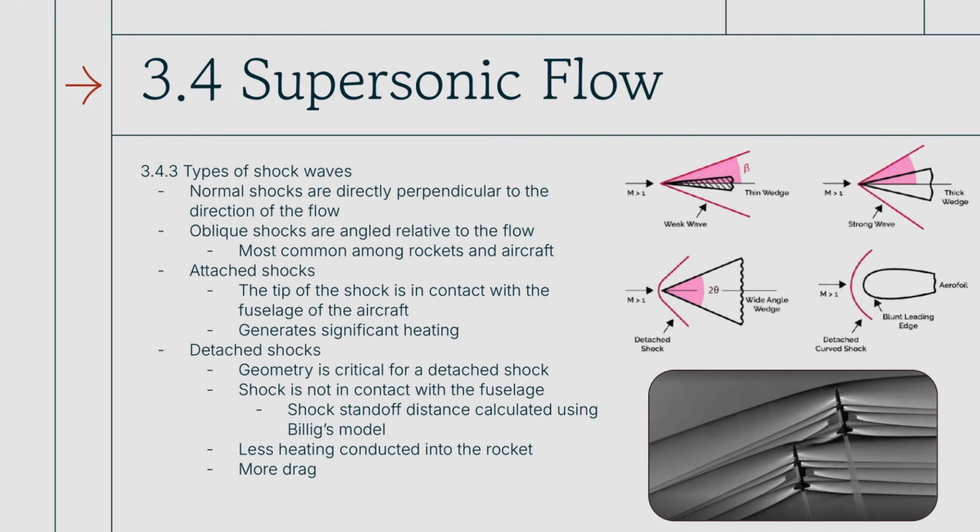What this results in is a lot of heat conducted into the object. So if your shockwave, which is just a massive, super high pressure region, is in contact with your object, then a lot of that energy from the flow is then being converted into thermal energy inside of your vehicle, and that's what creates a lot of heating.